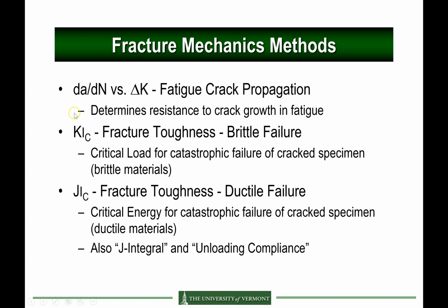So we're going to start with doing some fatigue in the test, but we are not going to measure this da/dN versus delta K curve in this lab. But it could be done. We're just not going to focus on this aspect. We're going to focus on the second aspect, which is the fracture toughness.